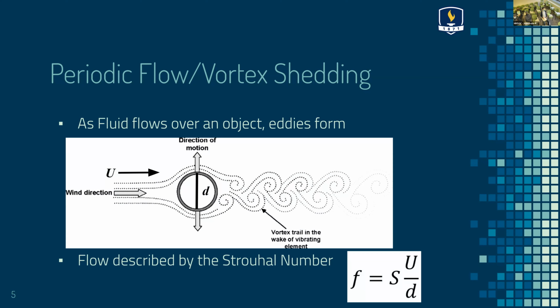As we get variations in pressure differences behind the object, we see these periodic eddies coming in behind. If you took a stick and swung it through the air and heard a whooshing sound, it's a similar phenomenon. And everything's governed by this equation here. It's simple. Frequency equals velocity over diameter times something called the Strouhal number, which is a dimensionless number that's common in fluids. It changes with respect to another dimensionless number called the Reynolds number, but generally the Strouhal number is about 0.2, which is significant in how we were telling if we were actually able to detect this phenomenon or not.